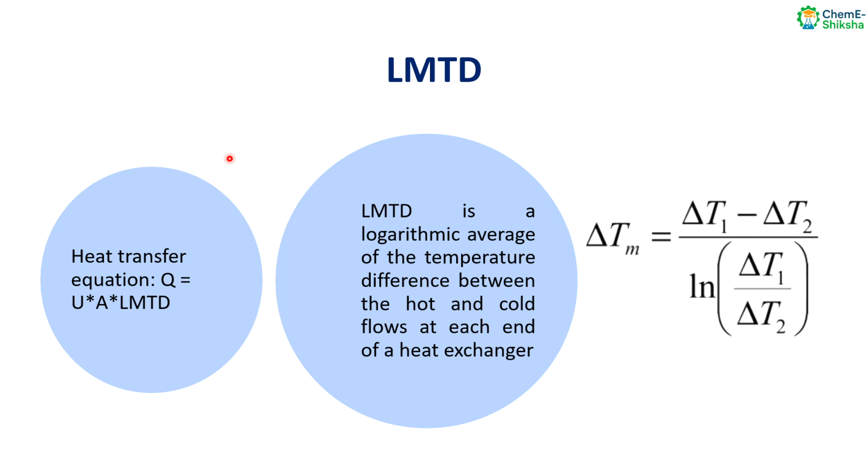So at which point we should take the temperature difference, we don't know. That's why it is more efficient to take LMTD, which exactly tells us the temperature difference between the hot and cold fluid, by taking the logarithmic mean.